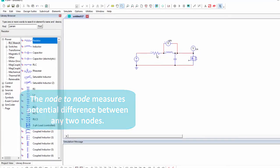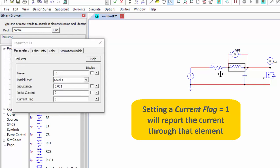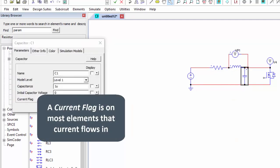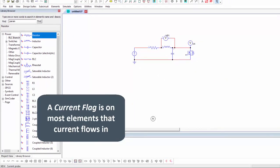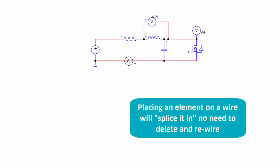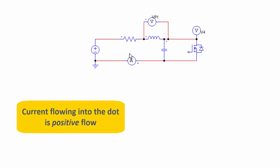And then we can also toggle inside of these elements this current flag. If we put that to 1, we'll measure the current flowing through these elements. So this is available on most elements. And we can also place, say, this ammeter on the return path here. If we just drop an element onto a trace, it will splice that in for us. So by just placing that in, it automatically inserts that so we don't have to do the rewiring.